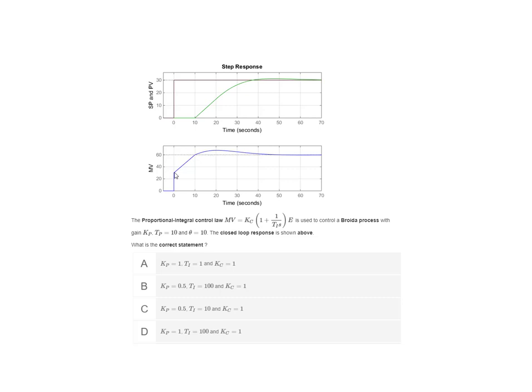And we had seen in this static or step response analysis of the PI controller that the time that is needed for the integral action, when there is no reaction of PV, of course, to add something that is equivalent to the proportional kick is the time of the integral time constant. So here you can see that the integral time constant is 10. A TI of 100 would cause something that would have a much smaller increase. So the correct answer is C.